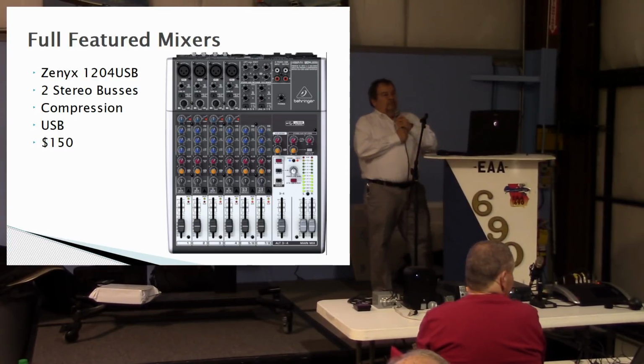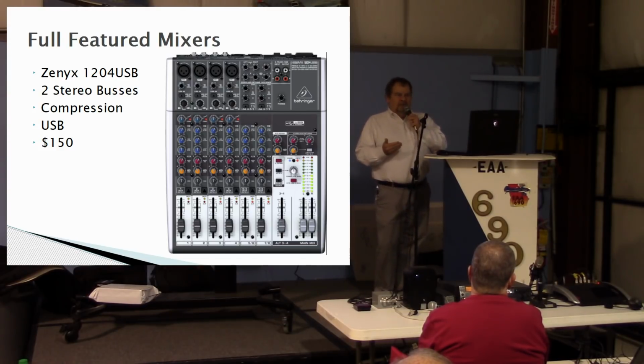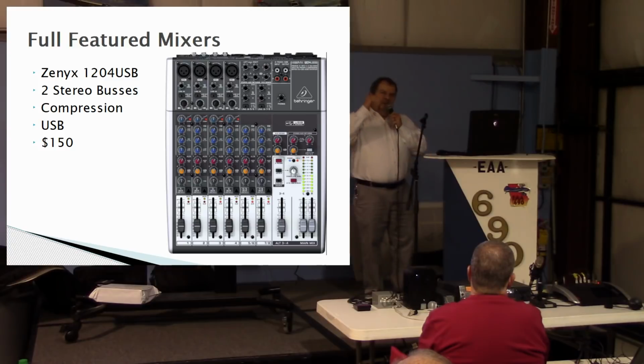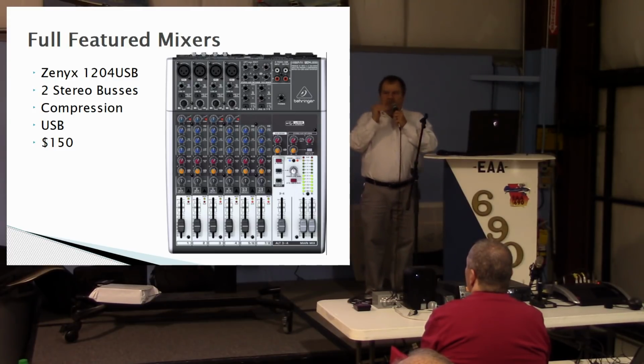Is it really more limiting rather than compressing? Well, no, it's a true logarithmic limiter. Well, a logarithmic limiter basically is a compressor. A limiter basically means that the audio gets up to a certain level and it won't let it go any higher, but it still gets up there just as loudly. They're soft limiters.